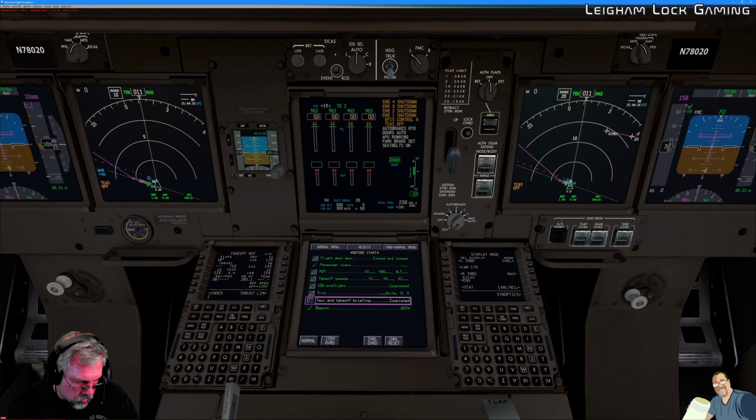For takeoff, we will be leaving the bleed air on. We will not be using any engine or wing anti-ice. No other noise abatement requirements that I'm aware of. Departure route. We'll be heading out at 301 degrees, climbing to 820 feet, turning right to 320 degrees, waiting on vector guidance to our first waypoint of Riggins.